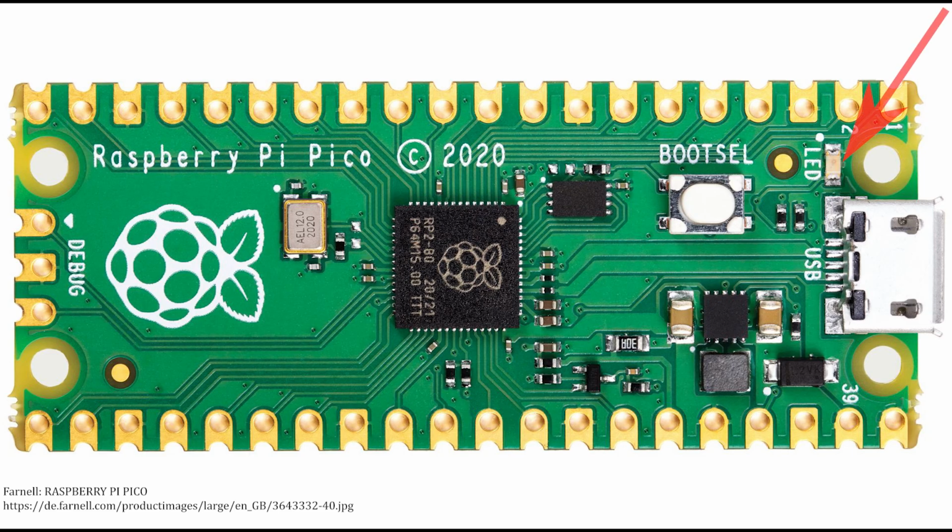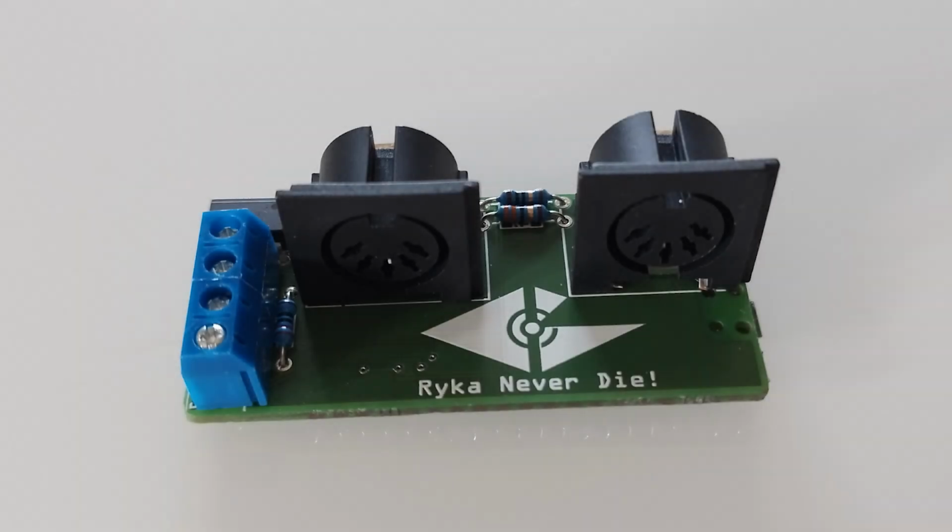Additionally, you can press the boot start button of the Pico during playback to block MIDI CC signals from being sent out to the Game Boy. Unknown CC signals can oftentimes corrupt the memory of MGB, so it's best to keep CC signals blocked when playing back generic MIDI files. You'll know that CC signals are being blocked when the LED of the Raspberry Pi Pico flashes at regular intervals.